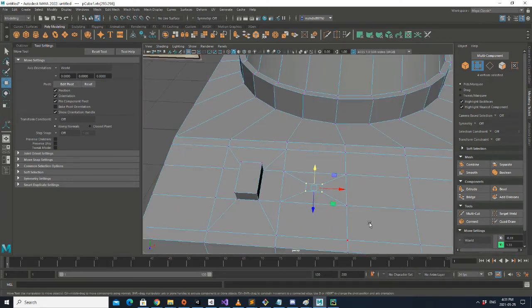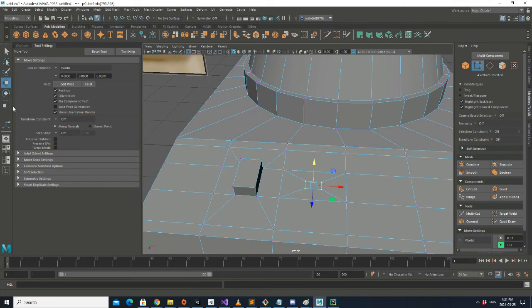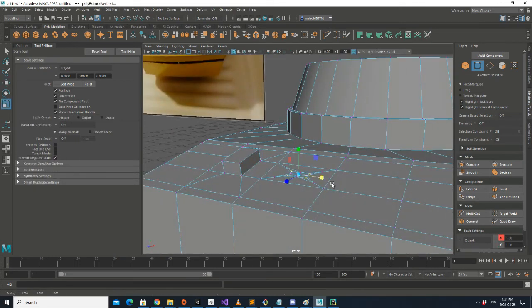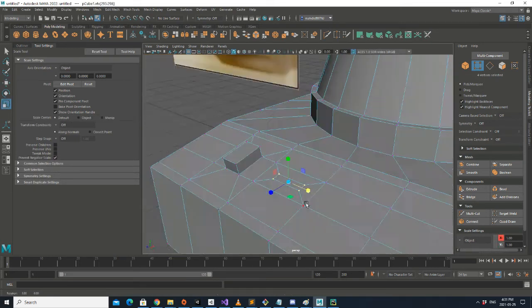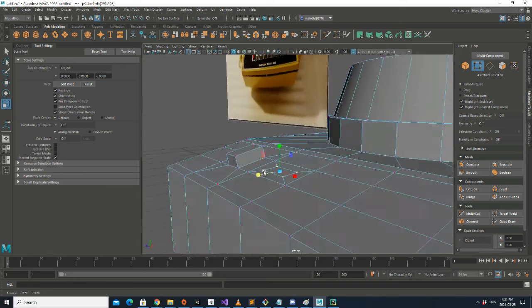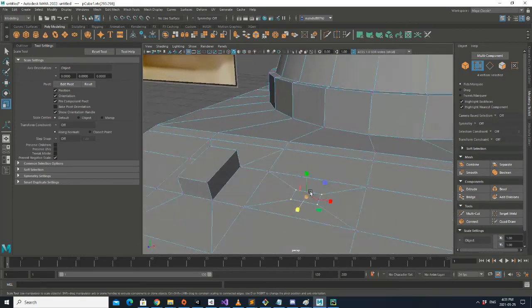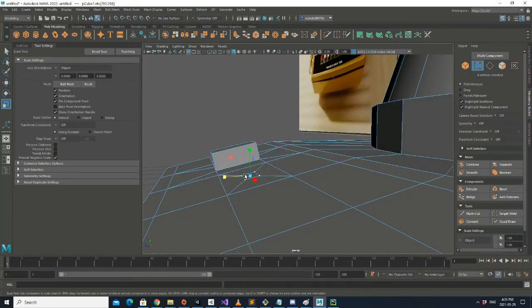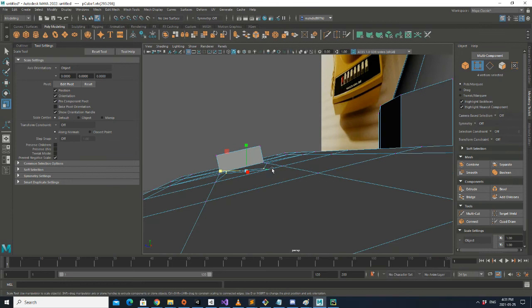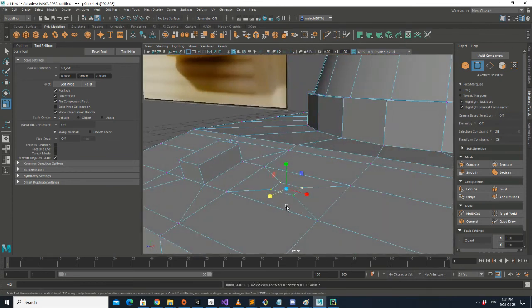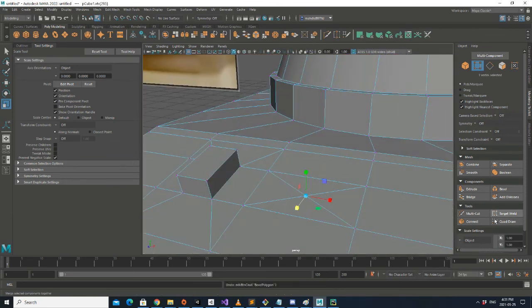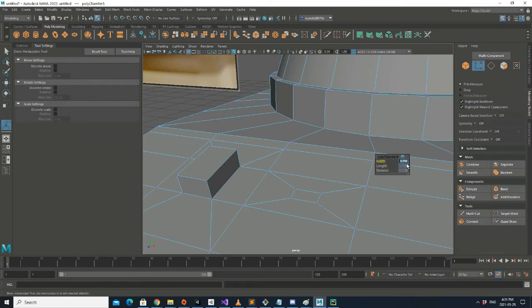And what you can do is to scale it along these dimensions, but it's not going to be a good way to do that either, because if you just take a look at that, this face is kind of having a slope, but if you scale it, you will see that you're making some unsmoothness here, and the best way is to use the number here when you're beveling.